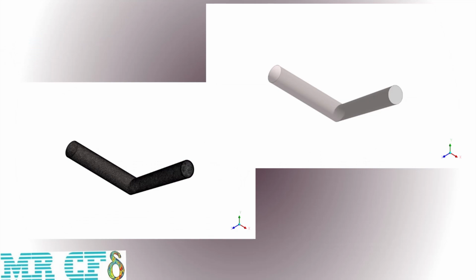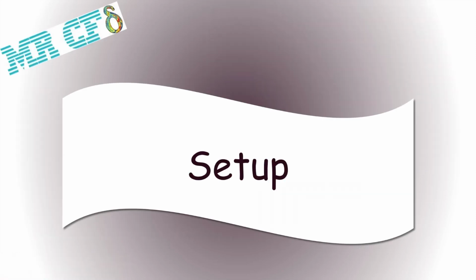The 3D geometry was generated in Design Modeler software. A bent pipe with a 3 cm diameter was sketched. In addition, an unstructured mesh grid was carried out using ANSYS meshing software, and overall, about 200,000 elements were generated. After using the gradient adaptation option, the mesh grid was refined and reached 1,450,000 elements.